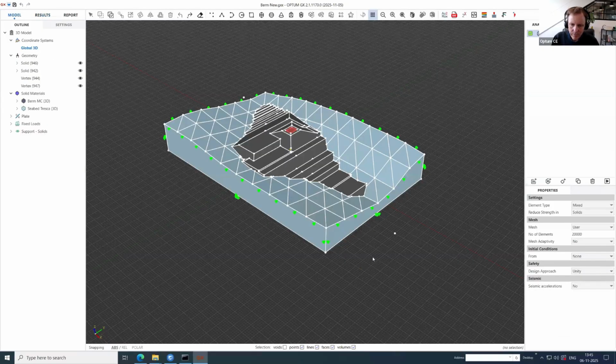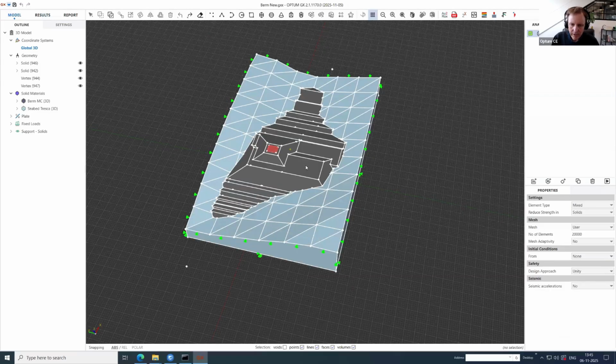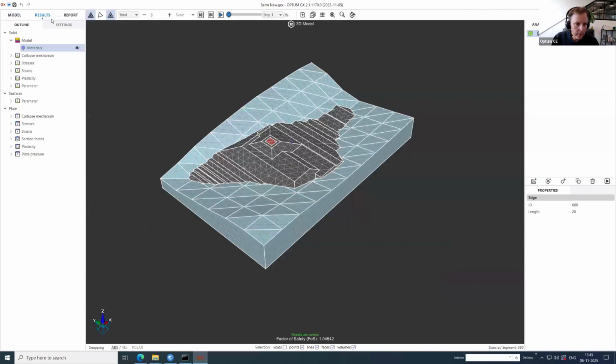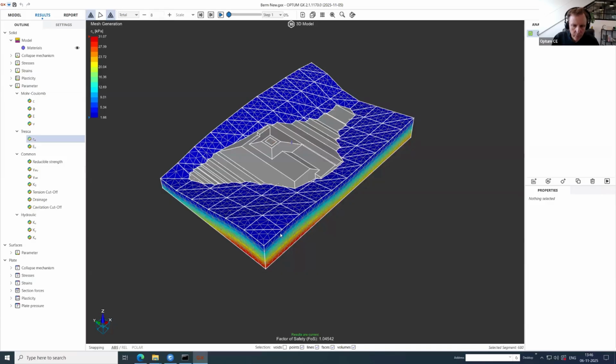So this blue part here is the seabed, and then the gray mass up here is rock that's been dumped on the seabed. Basically, it's to support a pipeline that comes here that spans this kind of little valley. And this is very, very soft clay, with shear strengths of a couple of kPa at the top, increasing somewhat with depth, but very soft sediments. Then you have this massive rock on top that, of course, needs to be stable.